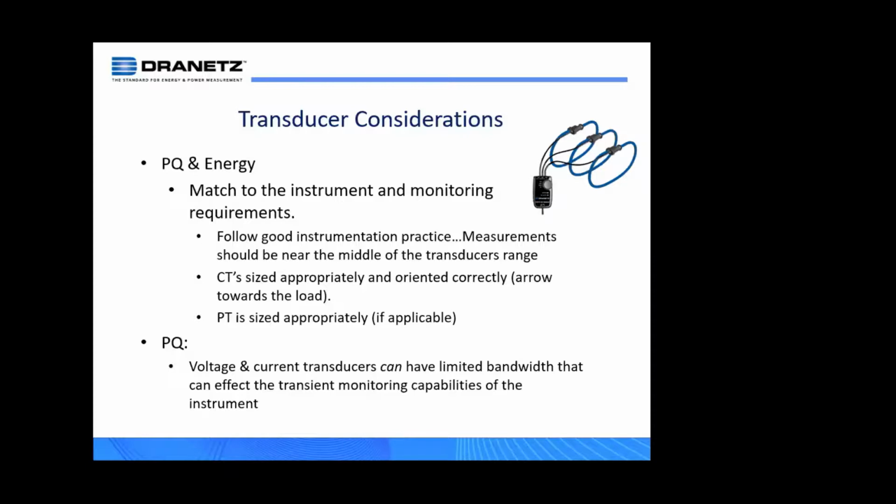Now, you may be able to go to a meter screen and compare it with another meter, and the amplitude compares favorably with the other meter, but that can lead you into a false sense of security. For power quality, you'll probably be okay. For energy management, you will not, because the CT will lose its phase accuracy. The phase accuracy, once you hit 10%, begins to gradually drop off the lower you go.